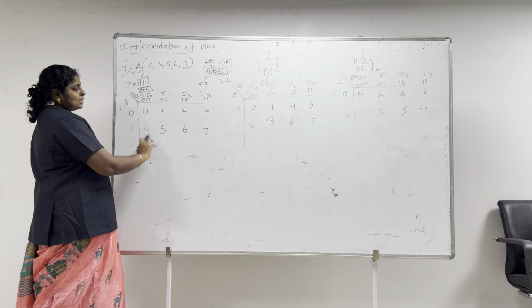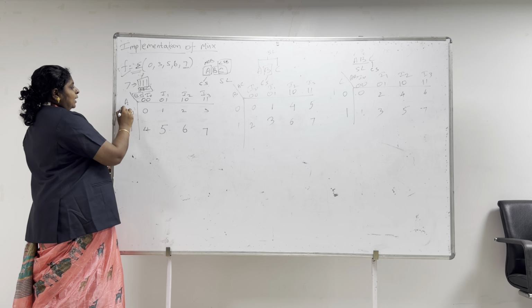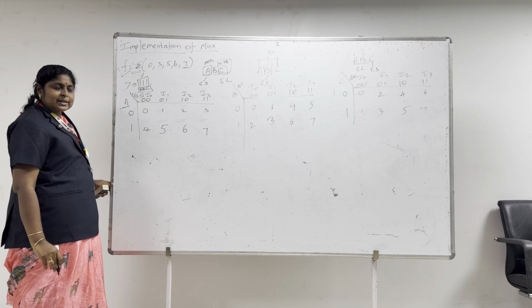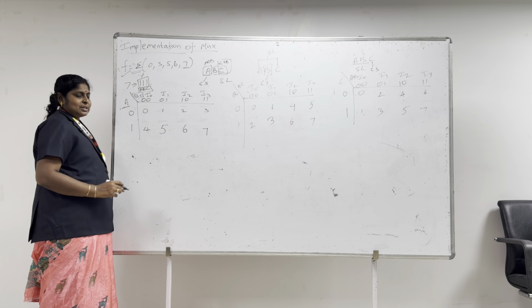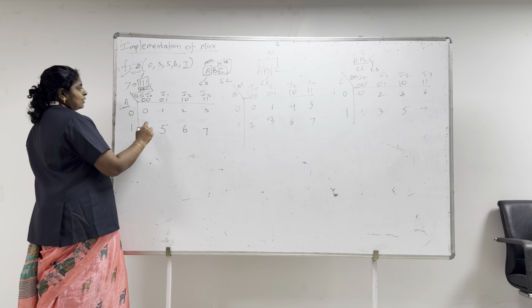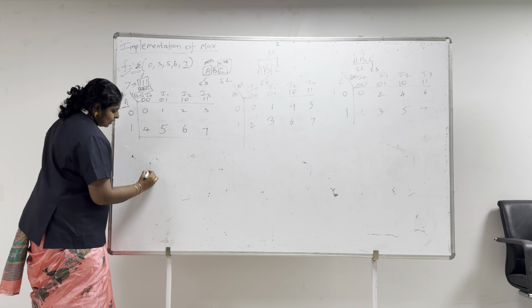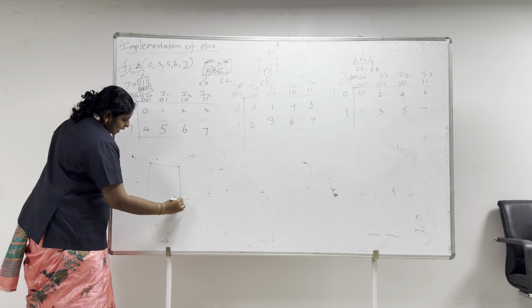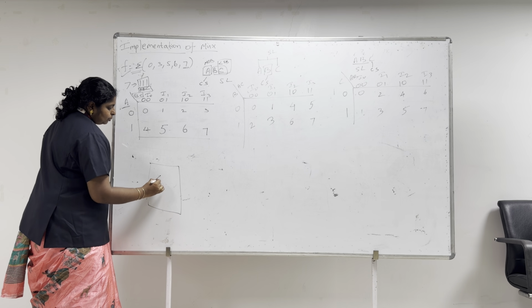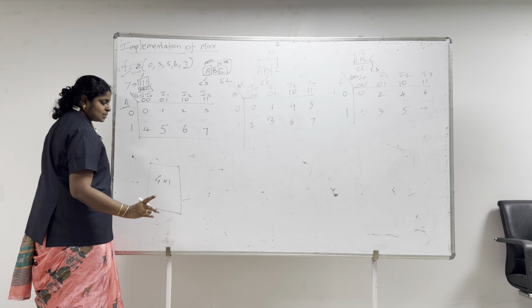First we will see this implementation, with A as my control signal and BC as my select lines. Based upon that, we have chosen 4 inputs. Therefore, our general structure mux will have 4 inputs, and obviously a single output.